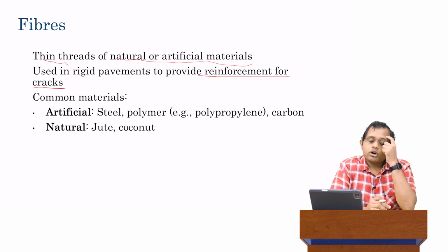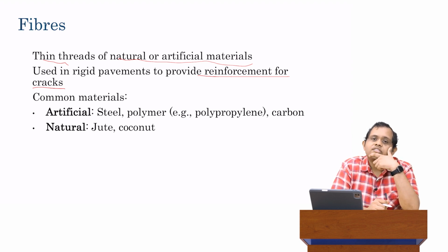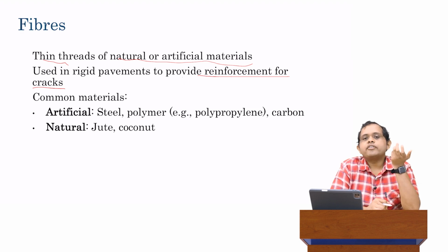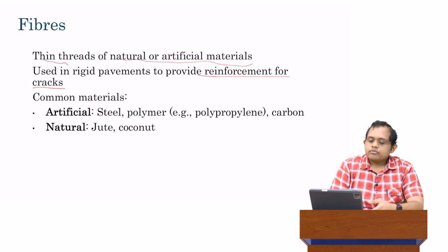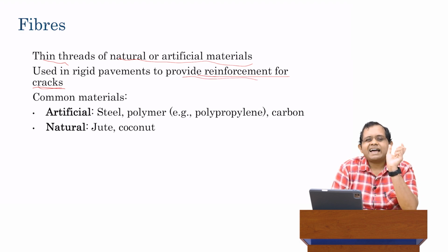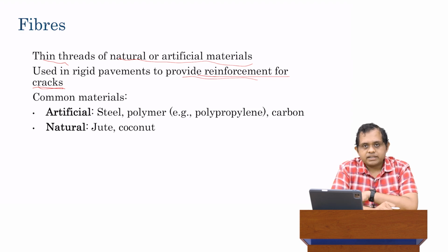This is very, very important, and we'll see a revisit of this concept in the next lecture, which will be on CRCP also. Whether it's steel reinforcement or fiber reinforcement, the purpose of reinforcement in pavements is not to add to the strength. Fibers do not improve the strength. Instead, what fibers do is they provide reinforcement for the cracks, that is, they prevent the cracks from opening up too much. They do not prevent the formation of cracks, and strength is basically related to formation of cracks.